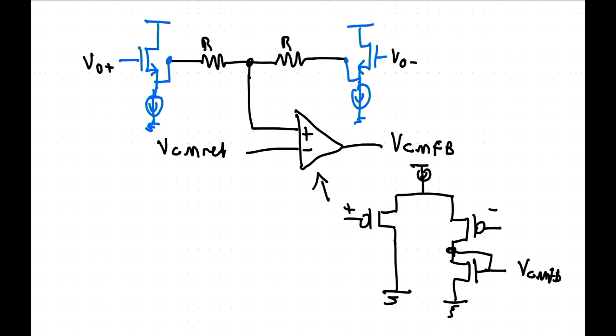So that causes both of the outputs to go like that. It doesn't matter. What matters is if it oscillates. Now that is bad. That's more important than trying to keep it dead stable, which is why I don't like to add extra gain in that loop.